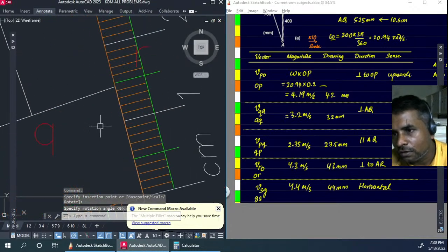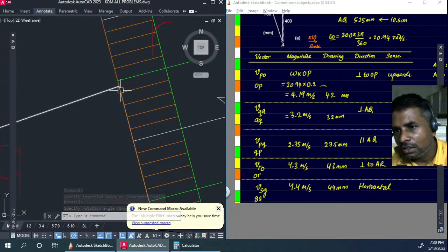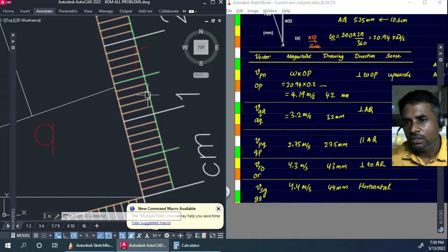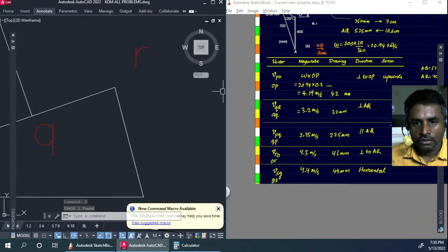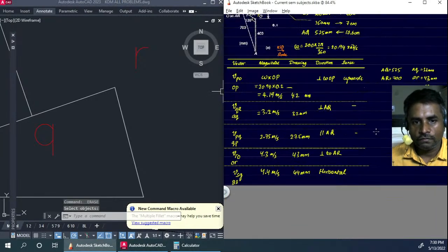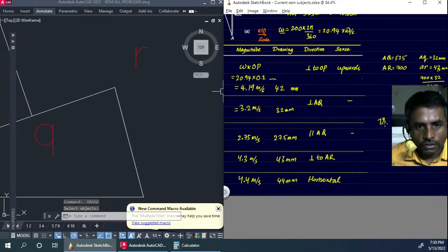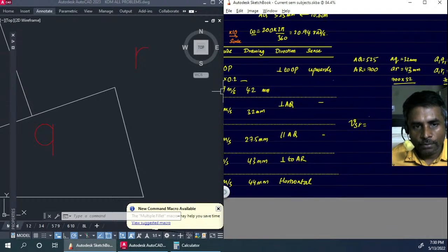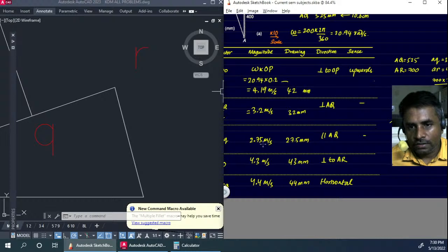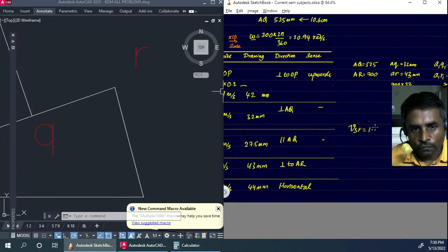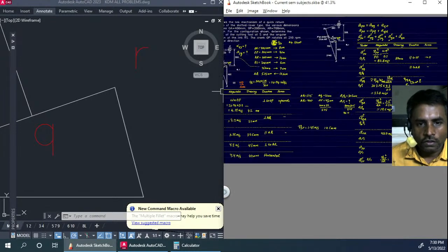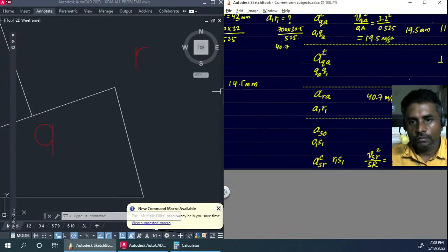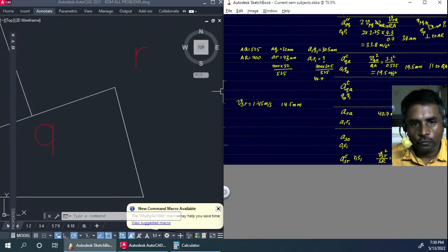Velocity of S with respect to R, it's very near to 15. I could just keep it in between 15 and 14, so 14.5. So we're getting 14.5 mm. Since we need to convert it back, we divide it by 10, so we'll get 1.45 meters per second. So that is the velocity of S with respect to R. We have to take that here. That's 1.45.